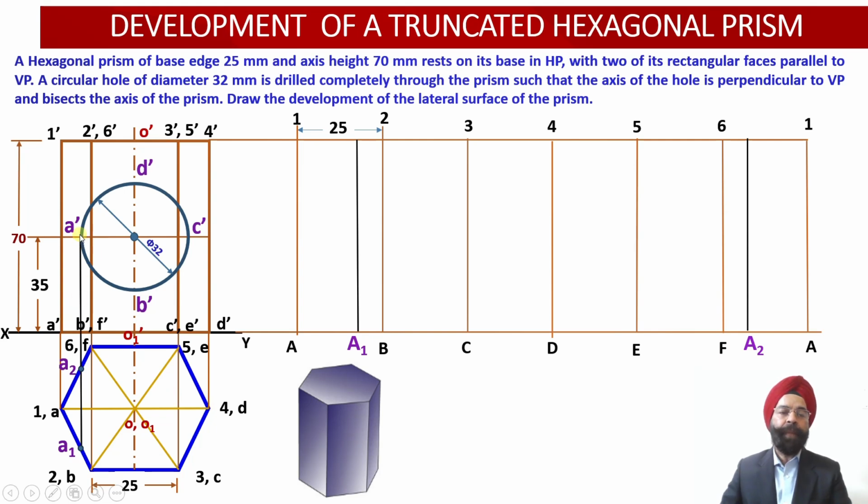So from the point A dash, if we draw a vertical projector into the top view projections, now we can check this black color projector which we have drawn from the point A dash, it has intersected with this base edge AB which is lying onto the front face of the solid at a point which we have named as point A1 over here.